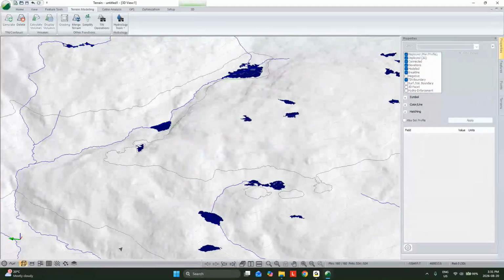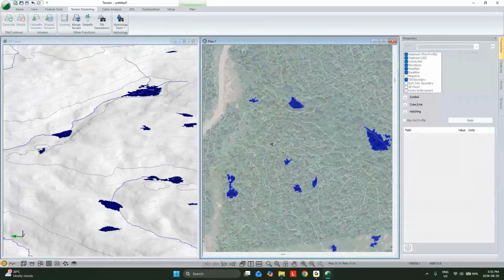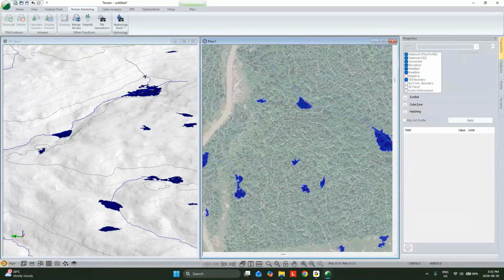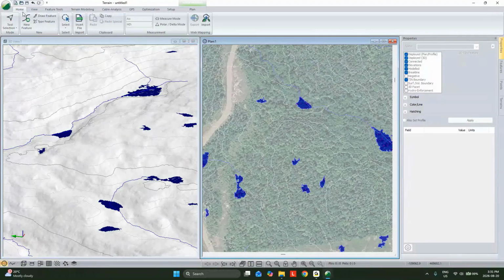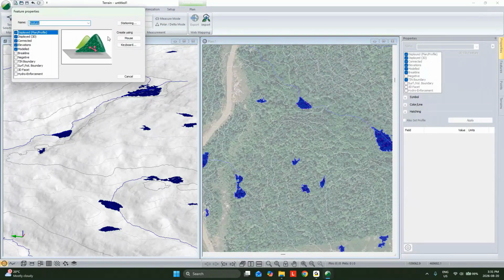Now I'm going to delete this. We're going to tile these side by side. So we may have a need for something that's entirely free-handed. But a lot of the time, particularly if we're dealing with building pads or something like that, we're probably best off with a little bit more of a hybrid approach. So we'll design a quick pad here. We're going to set our pad with a center line and a bit of a crown on it for a crossfall. I'm going to call this pad CL.